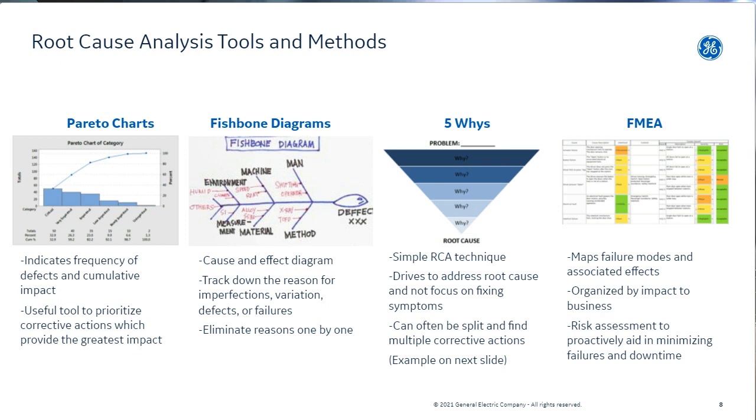FMEAs absolutely require this when you're going into production with parts. You're going to need this in your operation and production qualification. It's trying to map out all of the different failures that could happen and what are your mitigation methods to make sure that they don't happen. What have you put in place as planning to prevent failure? This is often a continuous improvement document, as you can think of everything you want and there will still be something that pops up and you end up editing that in the future.